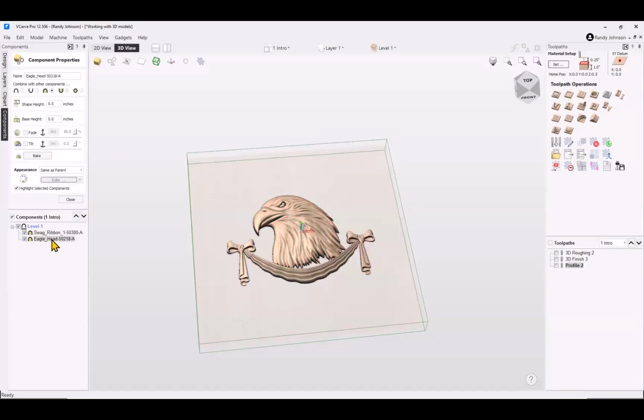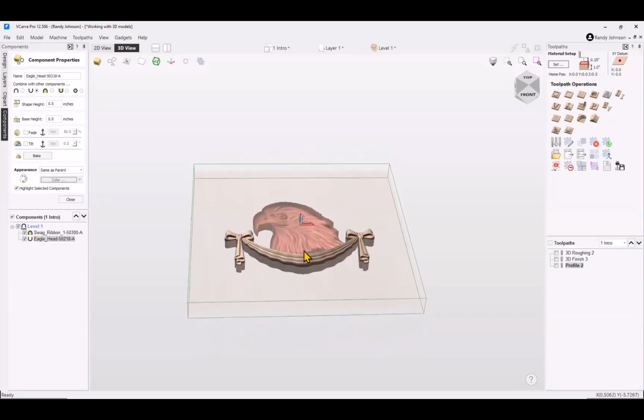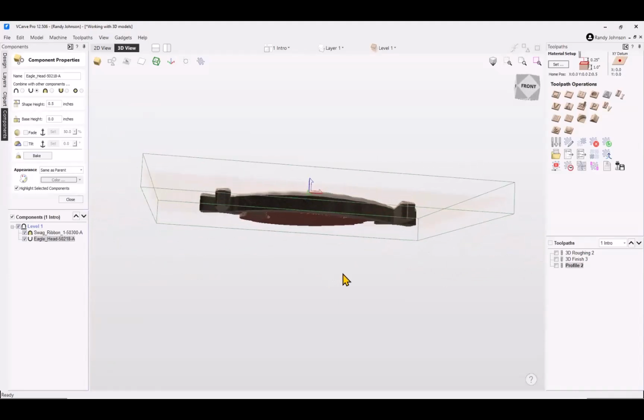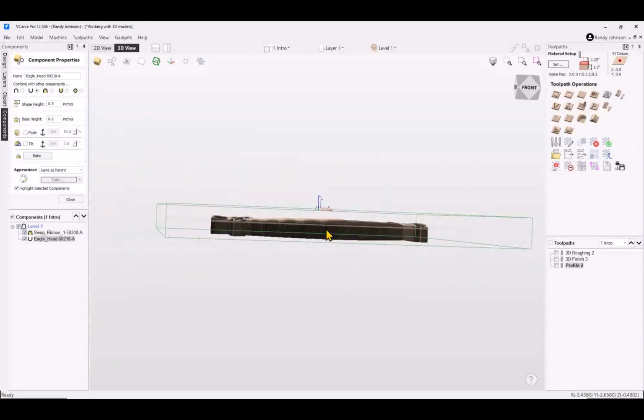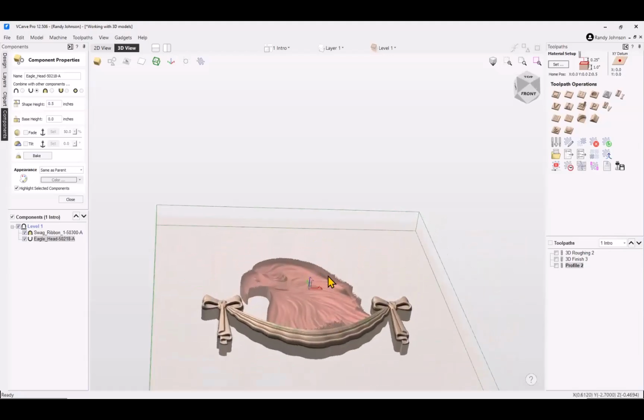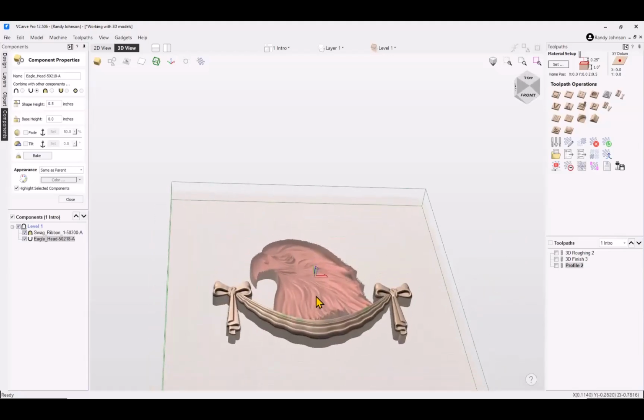But this one, which is referred to as subtract, actually has a major impact. Notice there, it now actually makes it a negative, and it actually now is going below the modeling plane by that amount. And we're going to be using that feature in the next demo, but that's what subtract does, is it actually does the inverse and goes down.